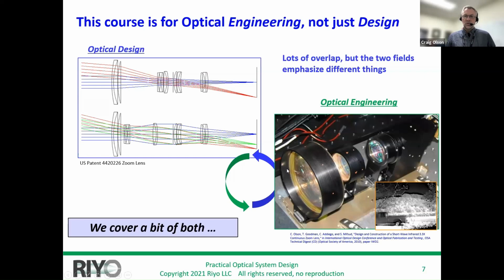And then these things need to work over temperature and vibration, because at the end of the day, you're going to hand it to somebody that has no idea what that is. They're going to bolt it in, scrunch it down as tight as they can, and ask you why it doesn't work. So, like I said, starting with the left, you have glass. You have to remember that we have to wrap metal around these pieces of glass, and not the good kind of metal like 80s hair bands like Kiss or Iron Maiden. We actually have to wrap aluminum or titanium around them and squirt glue in there, and they need to hold.